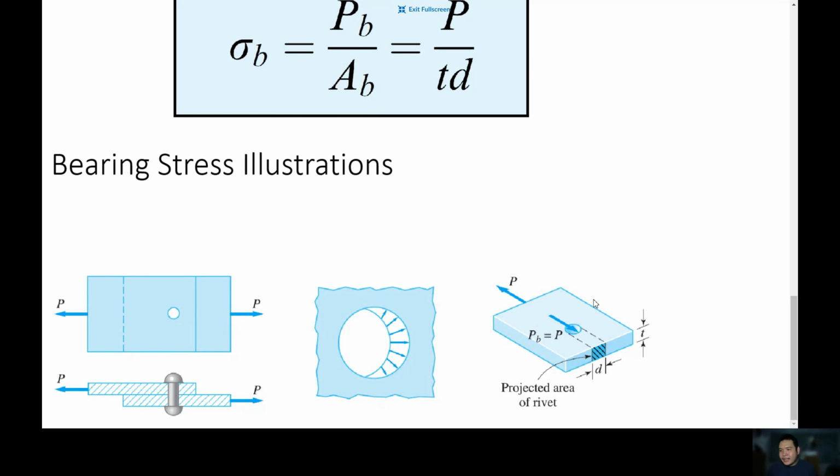So there are two tendencies when you put a hole. For example, take two papers pinned by a bolt, which is a pencil perhaps. Since the bolt has a greater strength than the paper, the paper will tear. Same concept here. Since the bolt has a greater strength than the plates, the plates are torn.